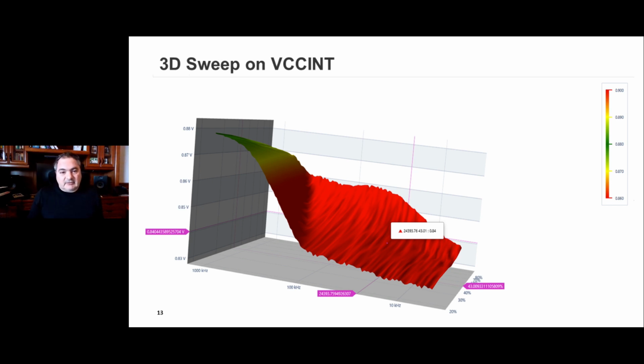The first one is where you sweep, as Rob did in that very brief demo. We sweep duty cycle. We basically have a voltage controlled current sink, which is what our LoadSlammer is, in the FFED or in the passive solution. And that voltage controlled current sink can vary the rise and fall time. It can vary the destination current, and it can vary the duty cycle and the frequency of the pulse as well. So that's a lot of permutations.